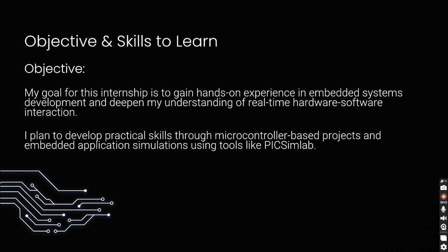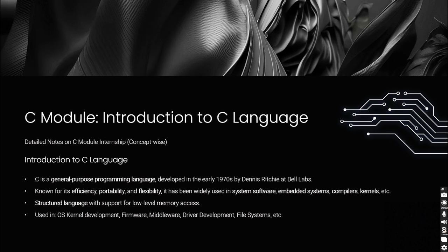We used MPLAB IDE for code development, Emertxe as a cross compiler, and PICSimLab for hardware simulation. Throughout the project, we learned real-time signal handling, embedded C coding, register level programming, and how hardware software components interact. I will be walking you through the logic and code explanation part of our project.